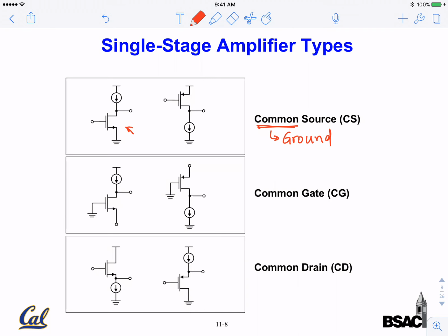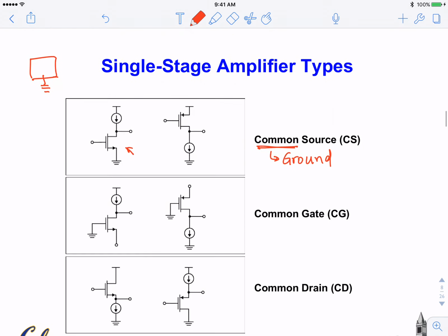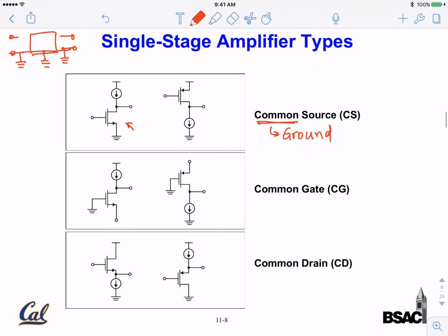You know, a two-port circuit. If you have a two-port circuit, right, it has a ground, and then the input is referring to ground as well, and output is also referred to ground. So whatever the grounded signal is, it is common to the circuit, the input, and the output. So the grounded terminal is referred to as common. So first type, source is grounded. There are 3 terminals in a transistor. So you can have 3 configurations.